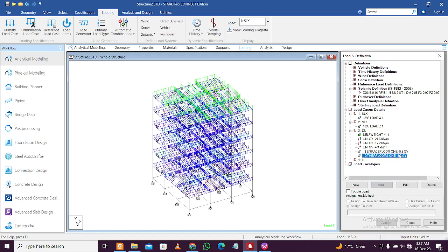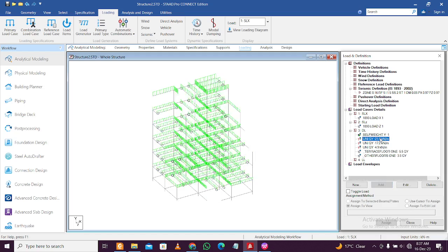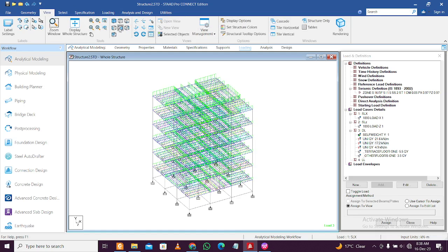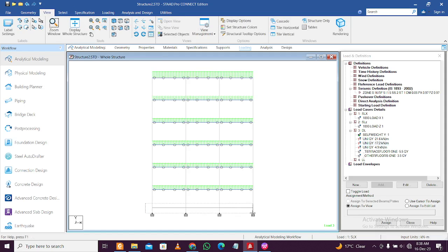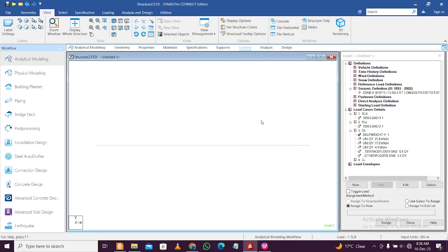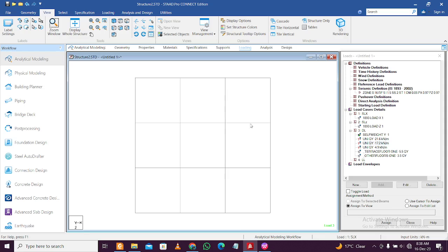This has already been defined. You can see the red and blue one is the selected one, already defined. So now we define the wall loads. First of all, let's start with 17, because this is the bottom floor. Go to view, go to front view, select this, and right click, this one only, then click on new view, click OK, and then we put the top view here. Make sure you select 17.2, then select this, Control, select this, and Control, select this. You have to press Control.